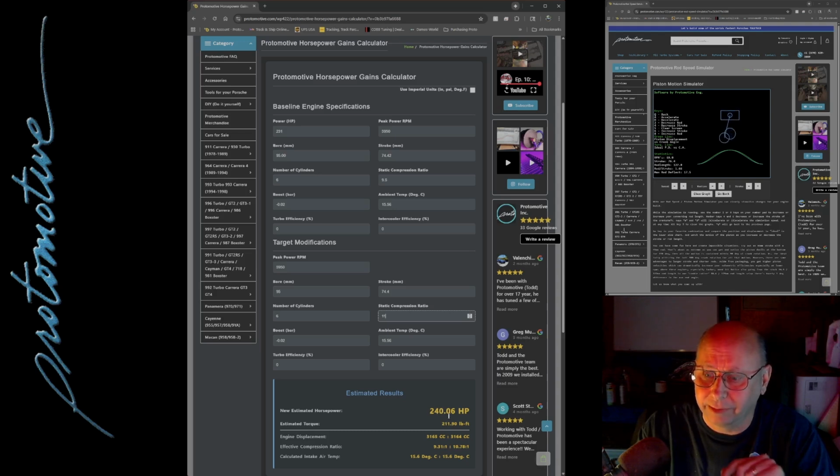Not really that impressive. And if you're out in California, you're stuck on 91 octane. It's not going to work well. You'll probably end up knocky. You'll have to end up running race fuel. So let's say we want to go nuts and run 15-to-1 compression ratio. Voila. If we had fuel that would actually support that, that would take us up to 257. But what's interesting is if you double the compression ratio, you're not getting great gains. So compression ratio is not what a lot of people think it is.